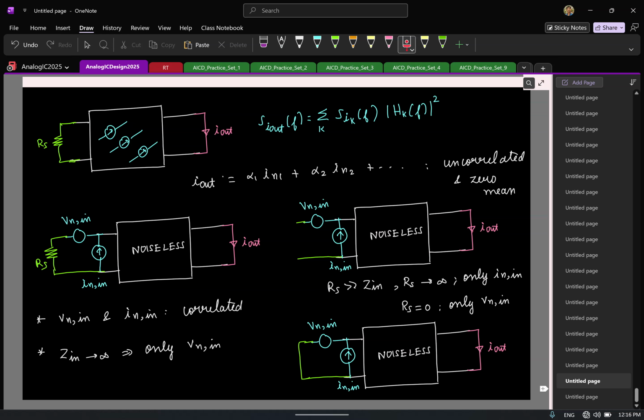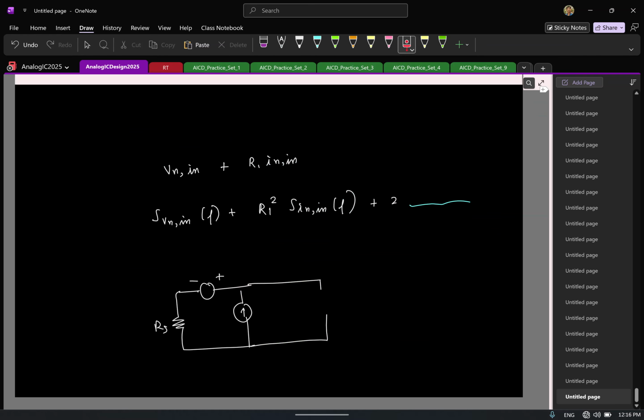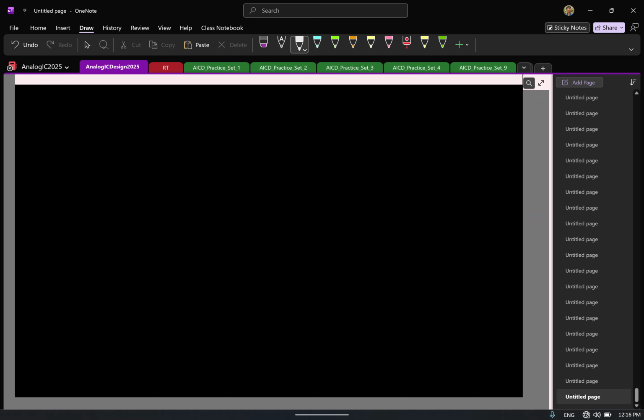Cool. So let's look at a few examples so that we get a hang of these calculations. Let's start with a simplistic circuit, a common source. This is your common source. I'll just draw the small signal equivalent. So the drain is grounded. I have RD here. I'm going to apply the input at the gate, tap the output from the drain.